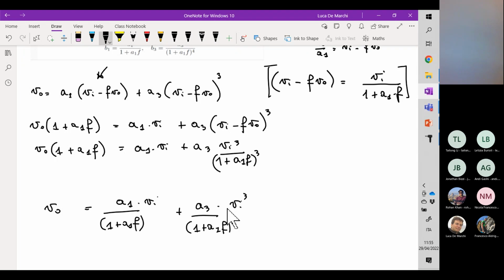In this case, the circuit is stable, but this may not be the case if the value of A0, the DC gain of the global circuit, which is again 1/f, changes. If we pick a smaller A null, let's say A1 placed at this point, or A2 placed at this one, let's investigate the stability.